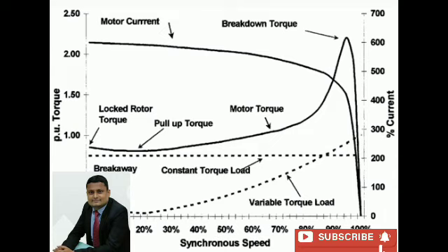So you can look over here, this is the go, this is the overhang, and this is the return, this is the finish. Start, go, overhang, return, and then finish. So resistance of the stator winding per phase, RSPH, equals 0.021 into LMT into TPH upon AS. LMT is the length of mean turn in meters, TPH is turns per phase in stator, AS is the cross section of stator conductor in mm square.